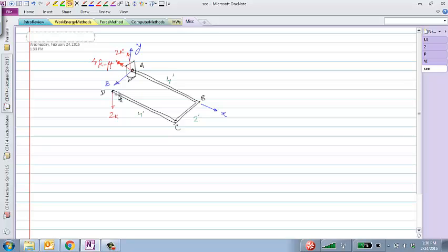Now, for the shear force diagram, hopefully you all saw that it was very similar to the example problems that we did. Shear is throughout 2, depending upon your convention, either positive 2 or negative 2 throughout the length of that bar. How about the bending moment? We know that in this portion of the beam, we would have a negative bending moment since it's going to bend downwards, down this way. It reaches 8 or minus 8 kip feet out here.